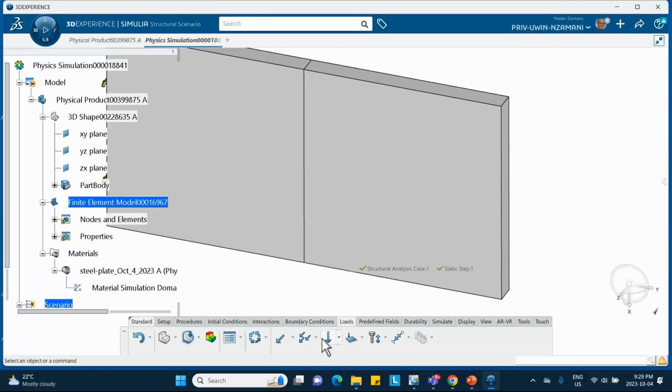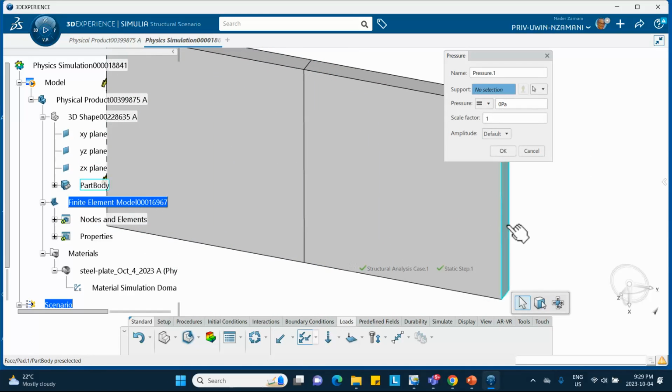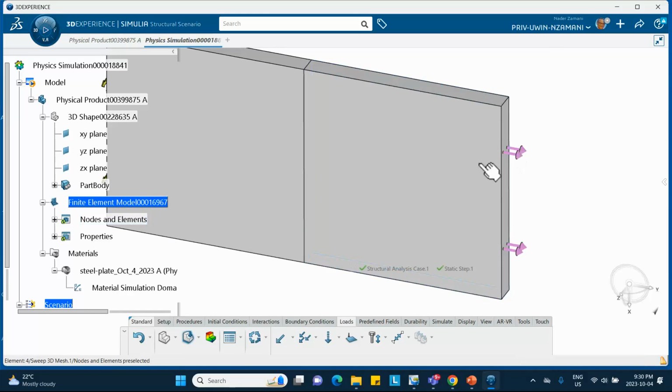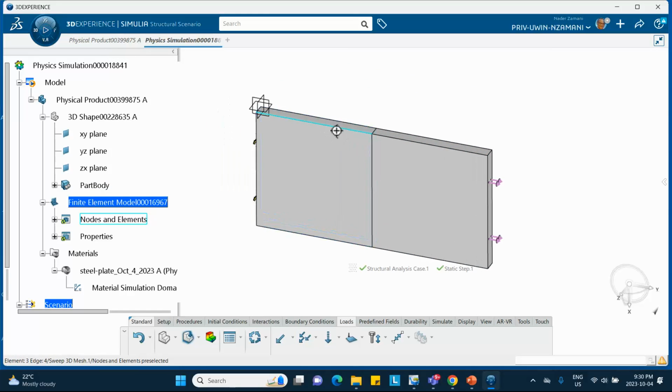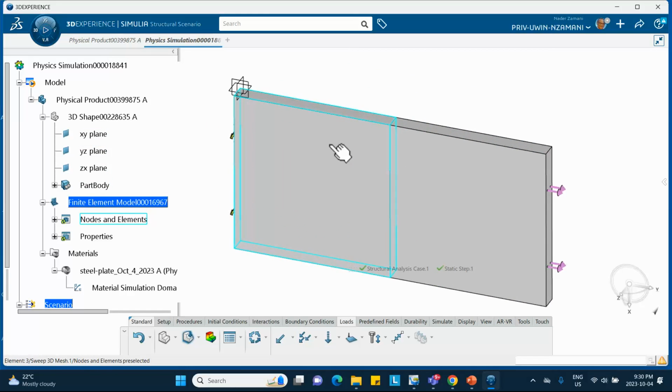So load pressure on that face 40,000 psi, minus 40,000 psi because I want to put it in the state of tension. There we are. The thing is that if I run this thing, it will bomb out because this can move, basically up and down and sideways under the roller. So what I need to do is to apply some other restraint here to prevent the rigid body motion. And there are many different ways of doing it.